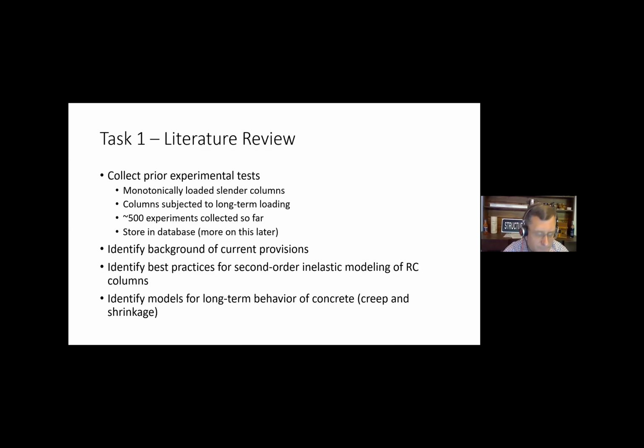So far, we've found about 500 experiments on slender and/or long-term loading columns, and we'll put those into a database format, which I'll talk about towards the end of the presentation. We also want to identify the background of current provisions within AASHTO, as well as the California amendments, and then best practices for second order inelastic modeling of reinforced concrete columns, and models for long-term behavior of concrete.